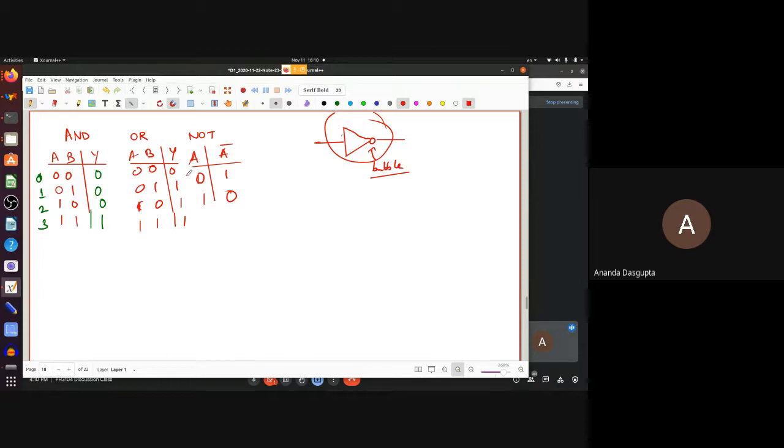So this is basically what the AND, OR, and NOT gate are. I hope everybody remembers them. These are the symbols. This is the AND. You write the AND with a dot, or sometimes just don't even write the dot. And the OR is written like this. So these are 2 arcs, and then there's a bent base here. And in Boolean, we write this as A plus B, although we should read this always as A or B and not A plus B.